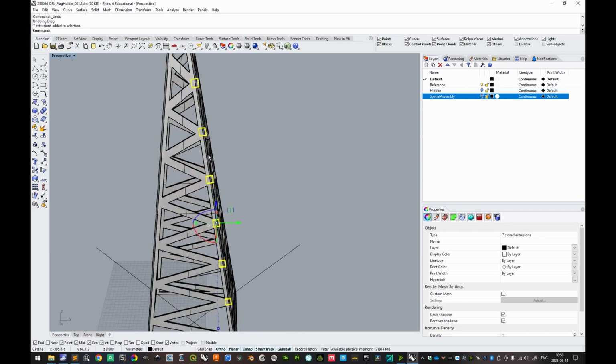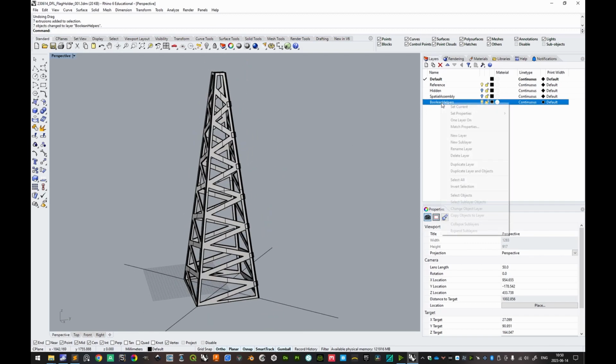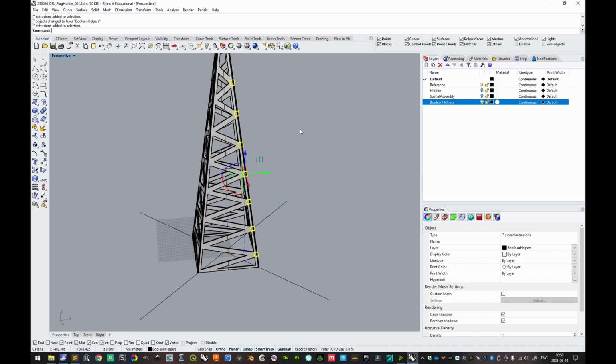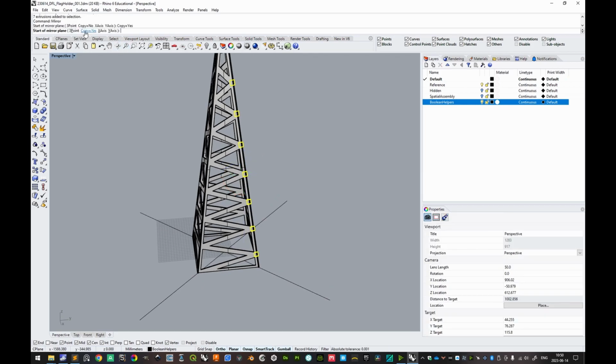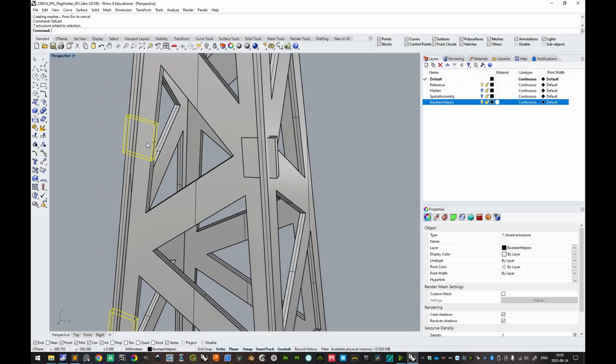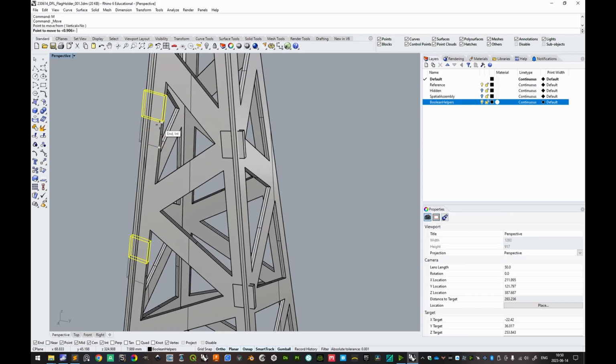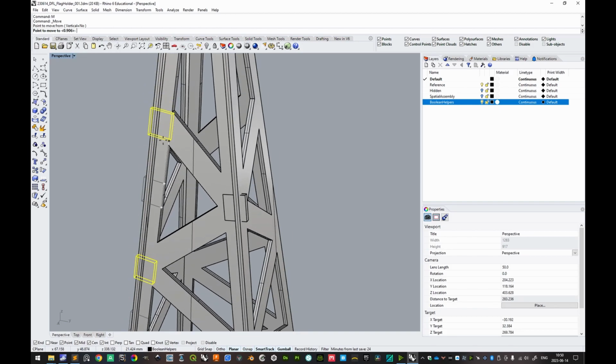Very good. We are going to use Boolean operations with this one, so we can do a new layer and type Boolean helpers. And then we'll make sure to assign these objects to that layer. Very good. And now selecting these objects, we can first do a mirror, and then a mirror with copy toggled on from the midpoint there to here. Very good. We can type Sel Last, that will select the lastly generated selection set of objects. And then we can move these, I think we move these up. So Tab to constrain, and then perhaps to there.